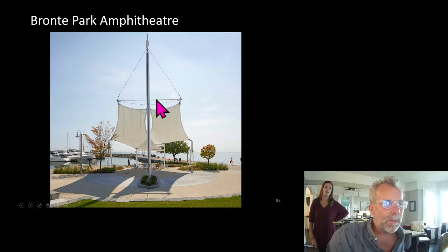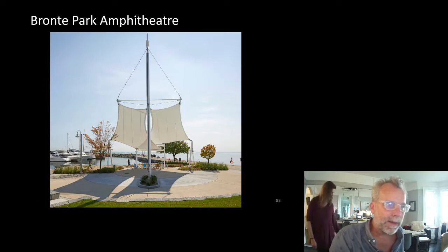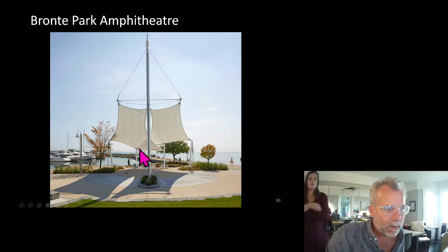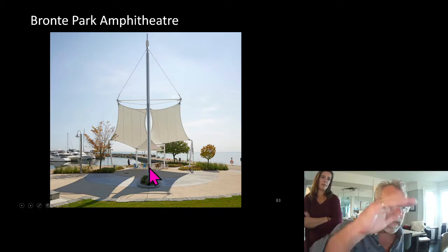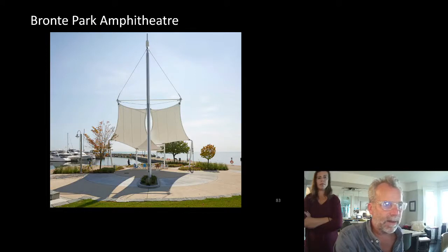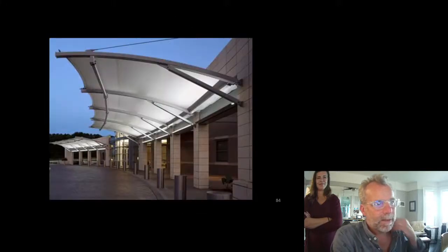So we'll talk about this more, but this here is what I call a floating spar. It's not actually connected to the vertical. So in a way, it's a tensegrity element. Tensegrity is when you have your compression elements floating in a web of tension elements without actually connecting to each other. The load comes back, the membranes come back onto these troughs here, and under the trough is a harp of vertical steel cables, with the idea that in the winter, the water runs out of the trough and freezes and creates an ice wall. I'm not sure if it's effective, but it's beautiful even if it doesn't.